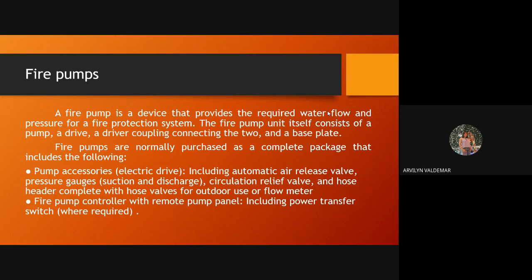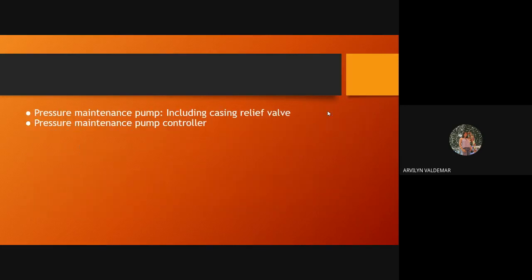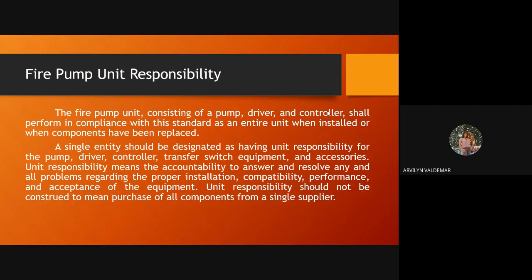Next is the fire pump controller with remote pump panel, including power transfer switch. Next is pressure maintenance pump and maintenance pump controller. Fire pump unit responsibility. The fire pump unit, consisting of a pump, driver, and controller, shall perform in compliance with this standard as an entire unit when installed or when components have been replaced.